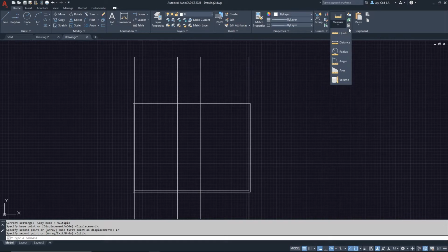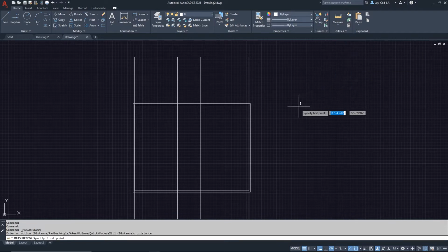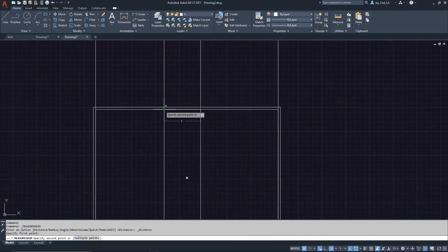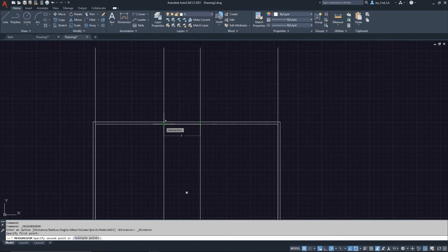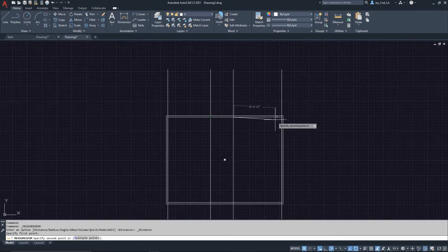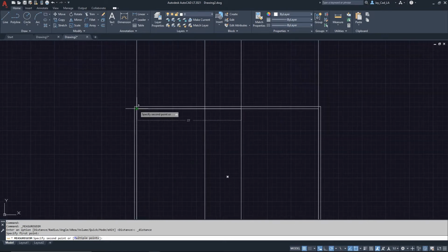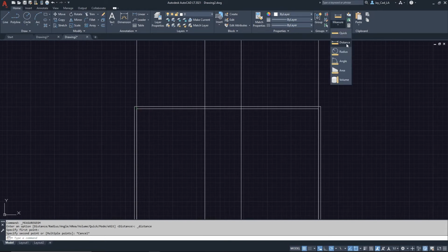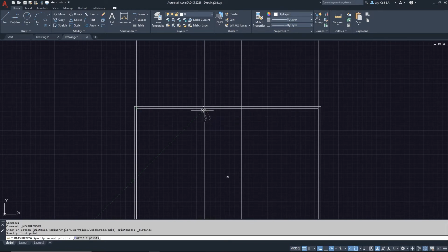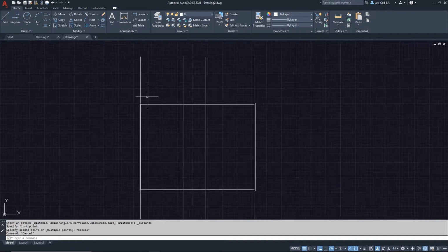And I'm gonna use the measure tool, which can be found here again in the home ribbon. Really, the majority of the commands you'll be using in AutoCAD are under the home ribbon. So from here, I'm gonna go to utilities, then go to measure, and then I'm not gonna use the first icon. I like to use this one called distance. I'm gonna choose that. And then I just want to see how much space I have between these two rays. I have 8 feet here, and then here I have 17, and then here, if I do it again, distance, okay, 15 feet, that's not bad.